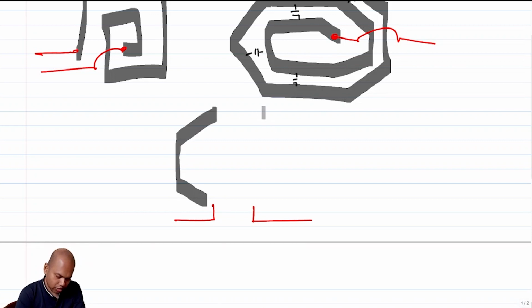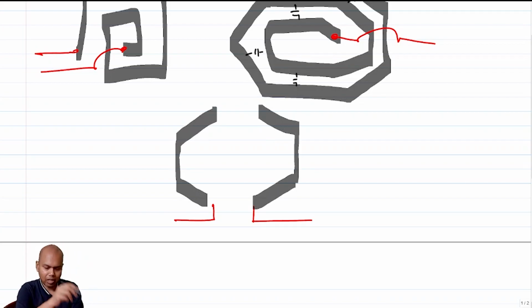And this also, so you can have multiple of these angles. For the sake of brevity, I am showing only 3 of these strips. Now when the signal goes to this, it comes at this point, I maybe go to a lower metal layer and quickly come up instead of having a big turn, right?